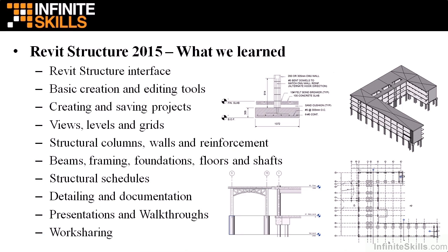We added bracing, trusses, and we created groups. Then we created floors on top of our beams. We created a floor system, and we cut shaft openings within our floor systems. Then, after we had everything built within our model, we started to document.